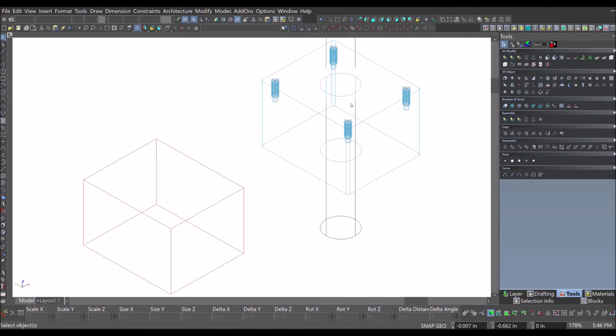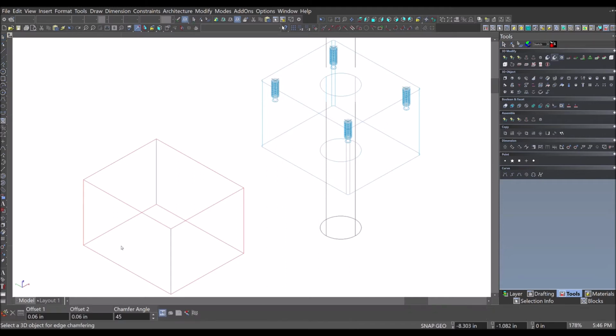I'm also going to put a 0.12 lead-in chamfer on this 1-inch hole, both top and bottom, so that a pin can fit through there, and so you want to be able to hit that hole easy enough. So you'll see that here in a second too.